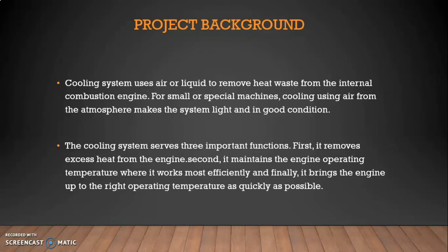Number 2, the cooling system serves three important functions. It is to make your engine be in good condition to use. First, it removes excess heat from the engine. Second, it maintains the engine operating temperature where it works most efficiently, and finally, it brings the engine up to the right operating temperature as quickly as possible.